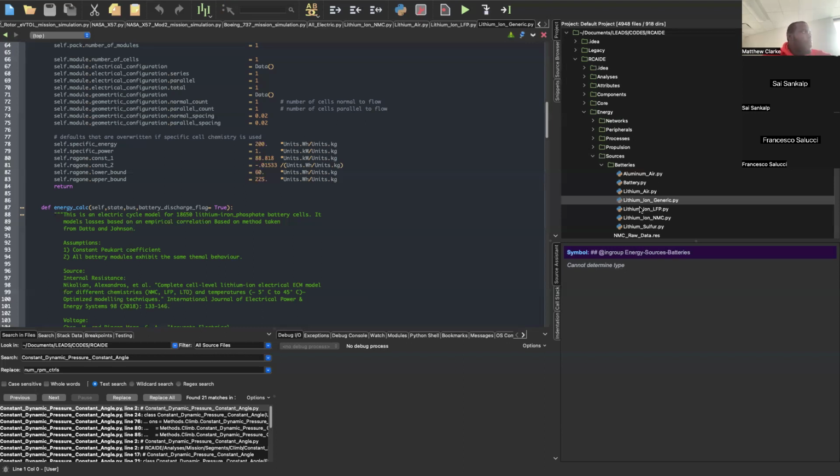So if you have like 8 propulsors and you know they're going to tilt at a particular angle, you just specify the angle of each propulsor, and then you can call that, let's say, transition phase 1, right? And when I was doing the Vahana aircraft, I had like 4 different configurations. One was at 90, one was at 75 degrees, one was at 45 degrees, one was at 25 degrees. I think the last one was at 0 degrees.